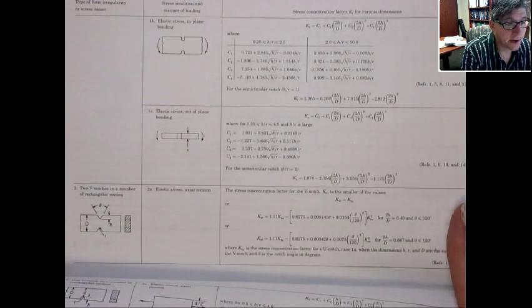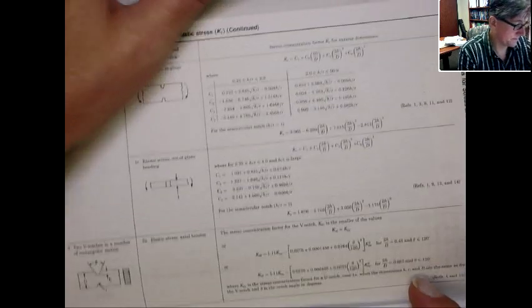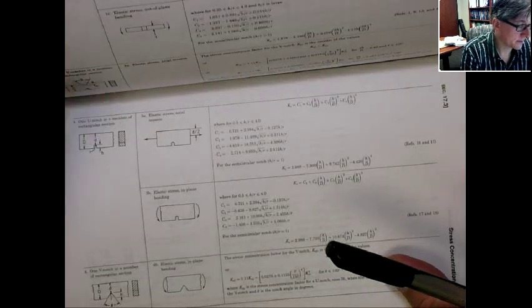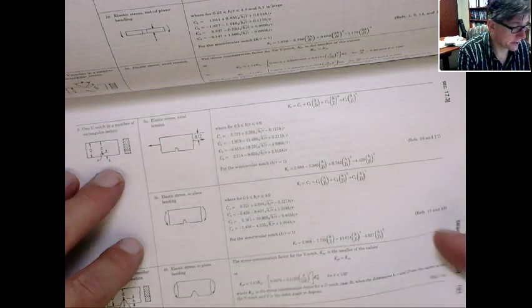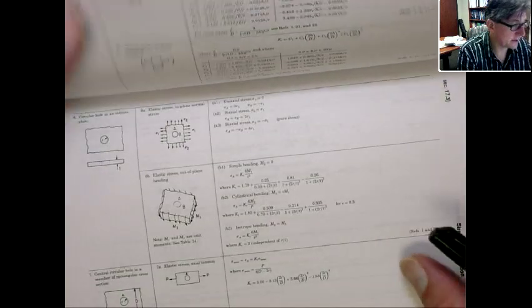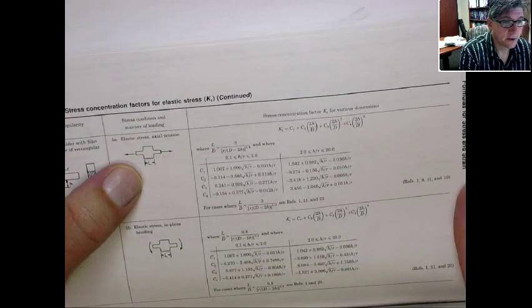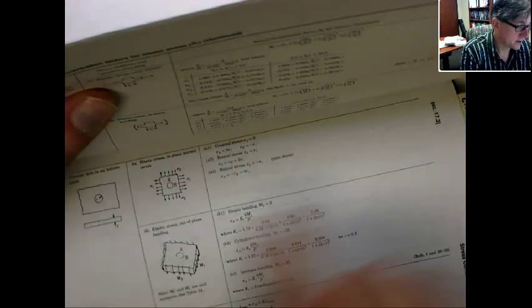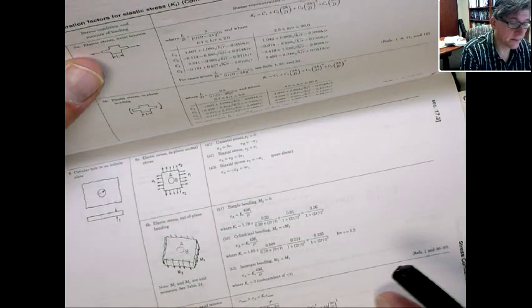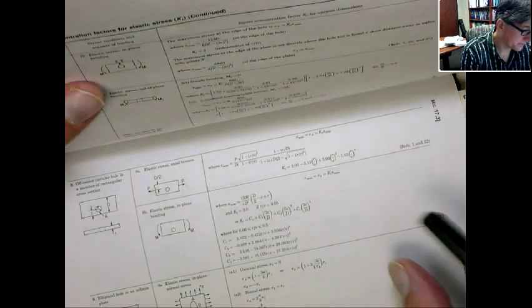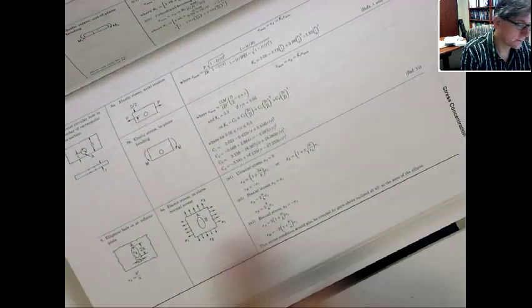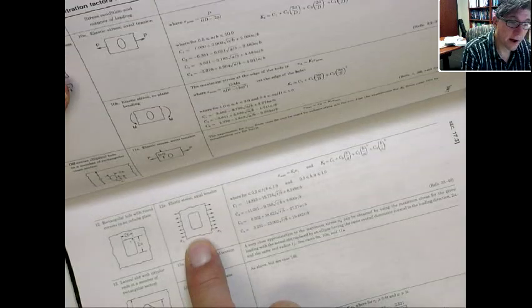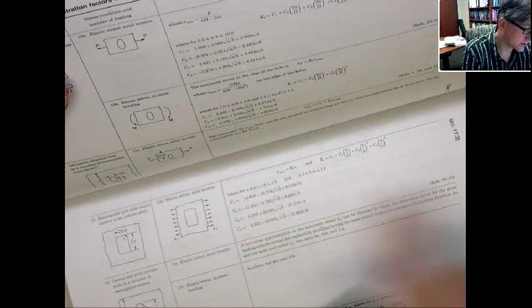Here's one for a V-notch. A notch just on the bottom in bending, a V-notch in bending, this sort of T-section, plate biaxial loading. So you can look all these up: elliptical hole, biaxial, right? A squared-out pocket that sometimes you see in weldment structures.